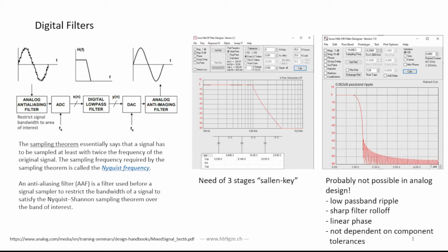So to make sure that we always fulfill the Nyquist criteria, we put a low-pass filter at the input, a so-called anti-aliasing filter. This anti-aliasing filter just reduces the bandwidth of your input signal to the limit of your Nyquist, so that your Nyquist criteria will always be met.